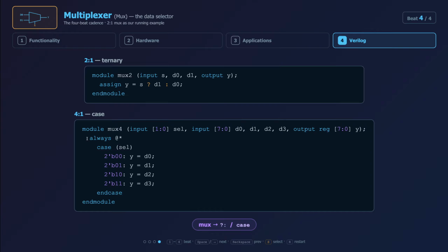All right, we're going to put this into an always block. I'm not going to describe what an always block does. There'll be another section in the book. If you're kind of fuzzy on always blocks, you can look that up. We are using a case statement here, which I think is relatively obvious if you've done any kind of programming that uses a similar type of conditional assignment statement. All right, so here's how it works in Verilog. We are conditioning on the input select. So select is 2 bits.